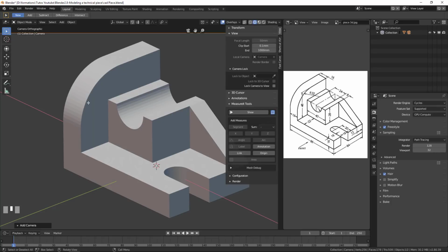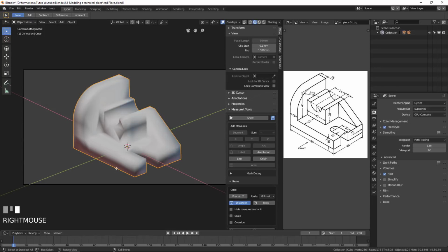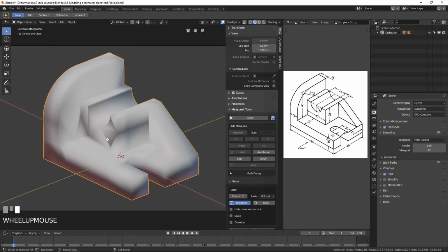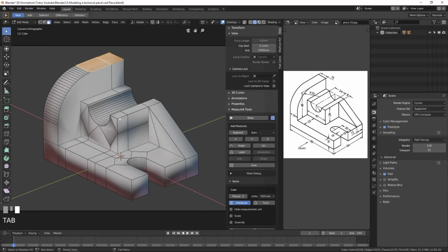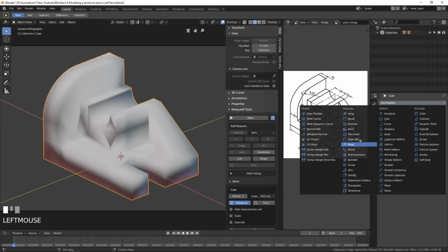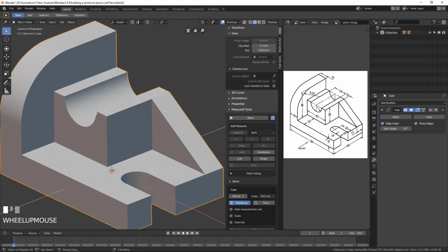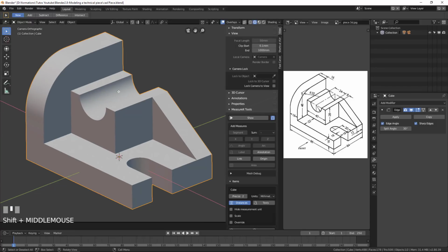We don't like this increment there, so we will select our object there. With a right click we will select shade smooth, and it makes crazy stuff like that because we have a lot of triangles everywhere and it's not easy to make shading smooth with this. So what we will do, we just go there into modifiers and add here an edge split modifier. So an edge split, what it does actually, it takes sharp edges like this, okay, and separates little objects. So this surface is an object, this surface here is an object, this surface is an object, and like this the smooth shading works better.